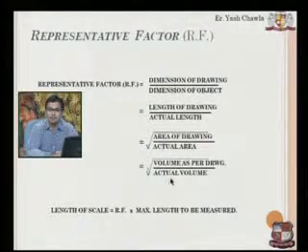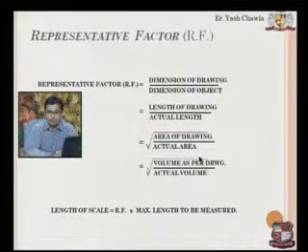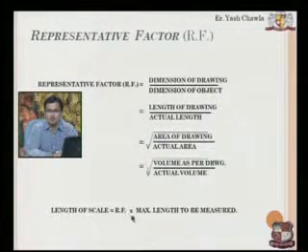And again, if you want to take out the scale in terms of volume, it will be the volume of the engineering drawing, or the volume as per the drawing that I have made, upon the actual volume, which factor will then again be taken the cube root of. And the length of scale that I need will be equal to RF into the maximum length to be measured, so that I can know what scale, or what dimensions, I can accommodate on my paper.